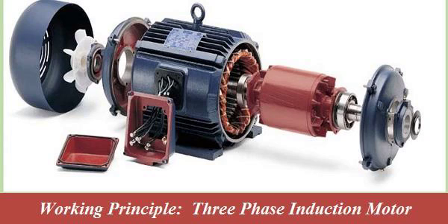Induction in rotor. As the rotating magnetic field cuts across the conductive bars of the rotor, squirrel cage, it induces voltage in them. According to Faraday's law of electromagnetic induction, the changing magnetic field induces a current in the rotor bars. This current creates its own magnetic field, which interacts with the stator's rotating magnetic field.